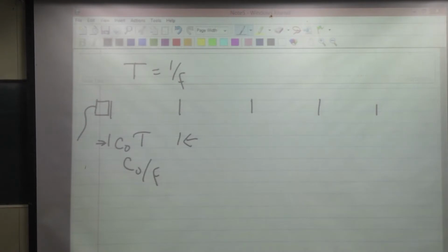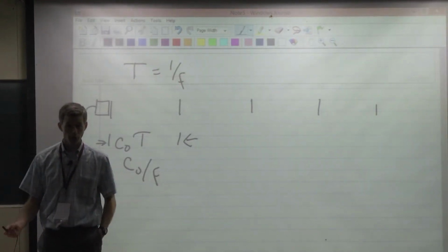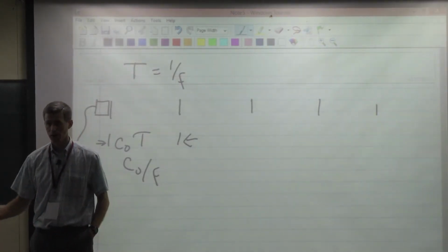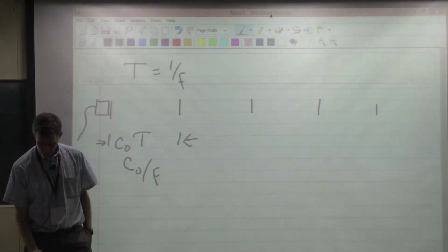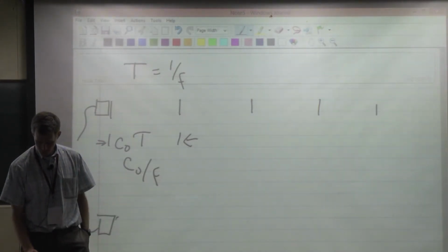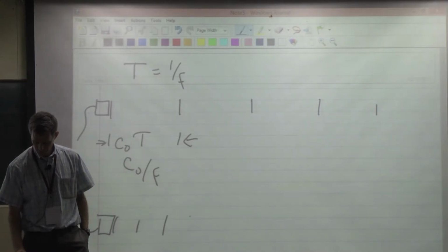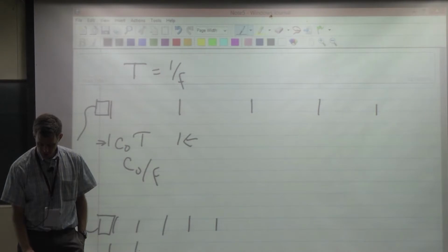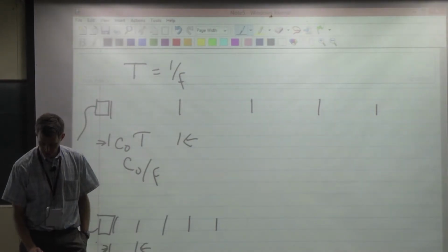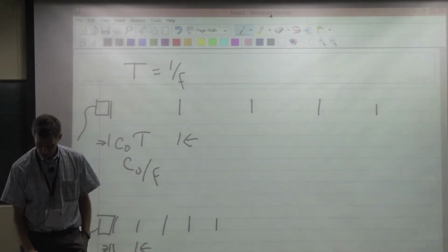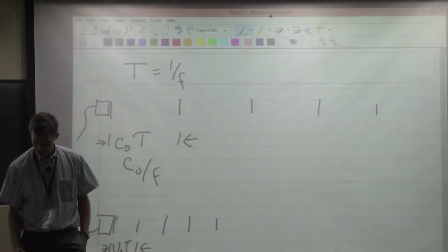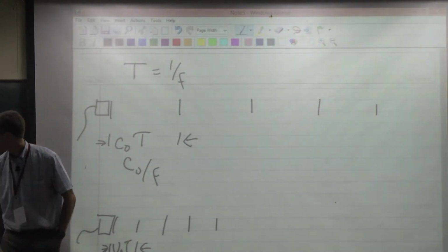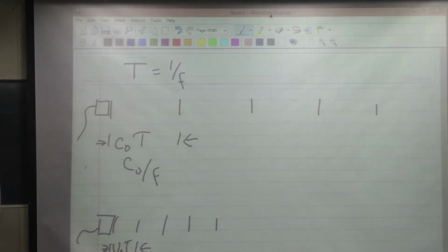Now, if my magic disturbance generator was generating vortical disturbances, these are getting propagated by the flow. What I would see would be this train of disturbances. The distance between those, they're not moving at the speed of sound. They're moving at the mean flow velocity, u naught times T. So my wavelength, what I'll call a convective wavelength, lambda c, is u naught over f. Okay?